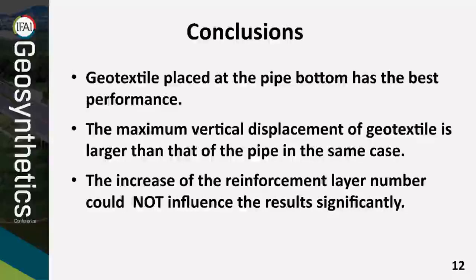So overall, in conclusion, if we have a pipe influenced by localized subsidence, we should reinforce the pipe at the pipe bottom, and only use a single layer.